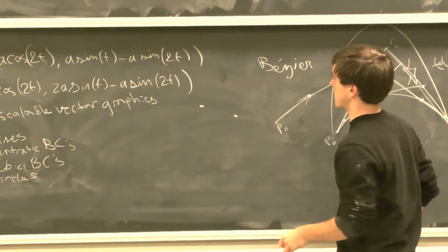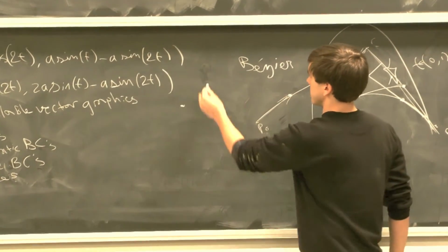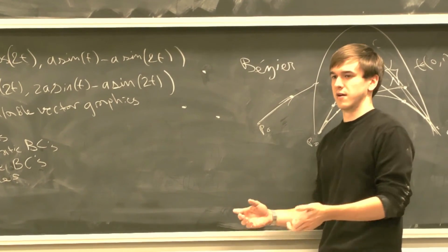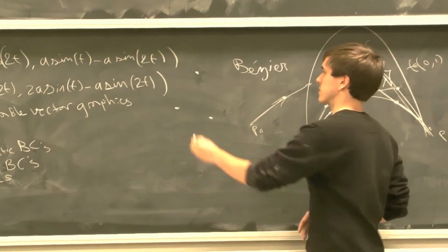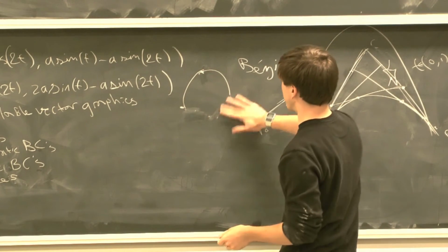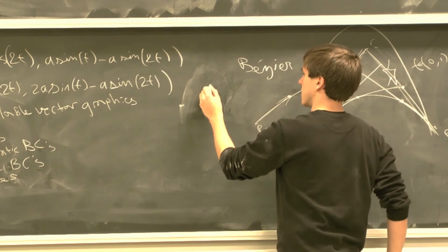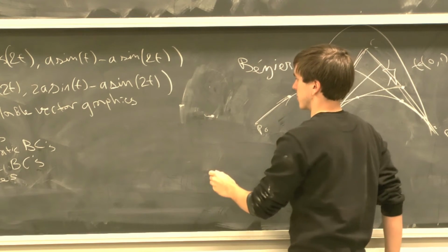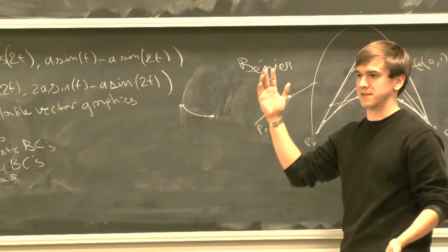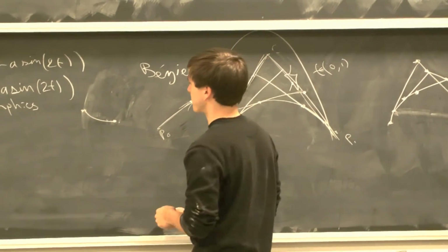You take 2 points and then you define a radius. So what would be really nice and happy is you pick 3 points, you've uniquely determined a circle, and then you pick which 2 points are the endpoints. Ta-da, or like so. That would be so easy, but that's not what happens. You have 2 points and a radius of the circle, and then whether it's a small arc or a large arc, and which side the circle is on. The math is really completely vomit-inducing.